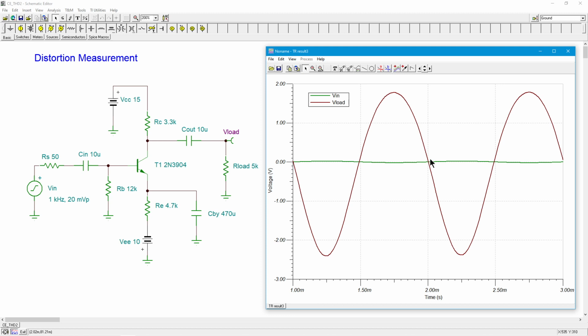Now those frequency components, because this is just a simple single sine wave input, are what we call harmonic distortion, because these new frequencies are going to appear at harmonics of the base frequency, the original frequency. And by a harmonic, what we mean is an integer multiple of that frequency. So we started off with 1 kilohertz. What I'm saying is this new waveform must have some 2 kilohertz, 3 kilohertz, 4 kilohertz, 5 kilohertz, whatever it takes to make up this waveform. So it's just integer multiples of the original frequency at the appropriate amplitude and the appropriate phase. When we add them up, we get the new wave shape.